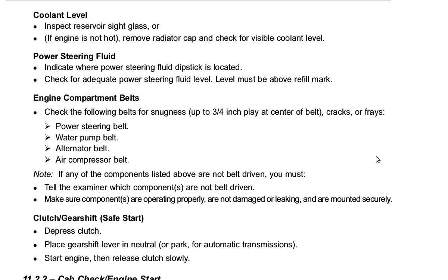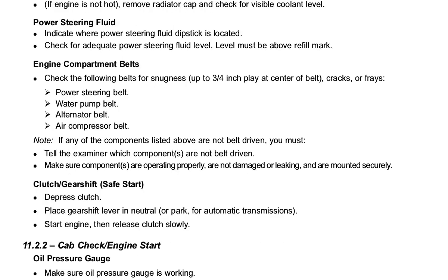Engine compartment belts. Check the following belts for snugness. Up to 3/4 inch play at center of belt. Check for cracks or frays. Power steering belt, water pump belt, alternator belt, air compressor belt. Note, if any components listed above are not belt driven, you must tell the examiner which components are not belt driven. Make sure the component or components are operating properly, are not damaged or leaking, and are mounted securely.